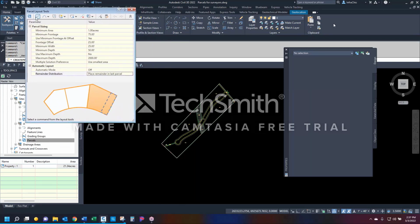That's awesome. Now, the first button over here, this is adding a fixed line. That will make a single line, point A to point B. Okay, that's all it does. It doesn't make a complete parcel. It just makes a line, one line, not a complete parcel. Do I need to add an arc from a line? I can do it 2 different ways, 3 points or 2 points and a radius.